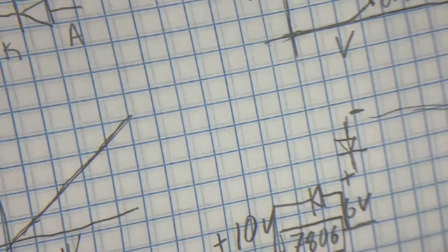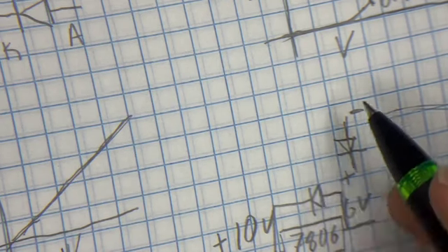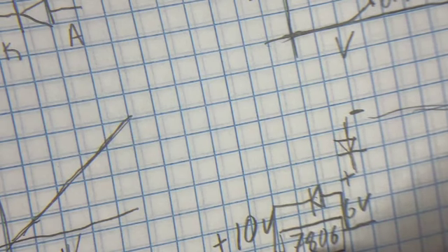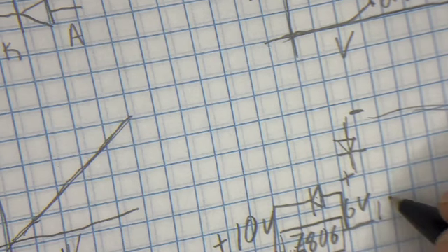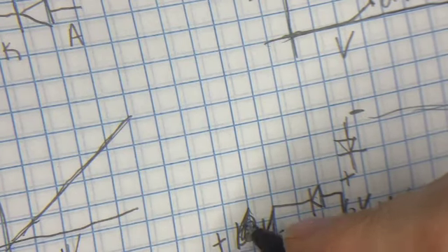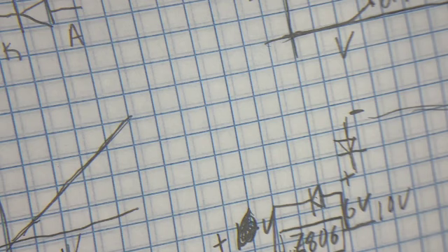Right? Because this doesn't understand the whole concept of all of this. But this diode here, or a diode that's inside some of them like this, will cause this current to just go back here. And the only thing that gets damaged is this little diode, which can handle a pretty large amount of current. But essentially, let's say you put the 10 volts here, ground here, and you're looking at getting the 6 volts here, right? Put it in backwards. That's the setup, right?